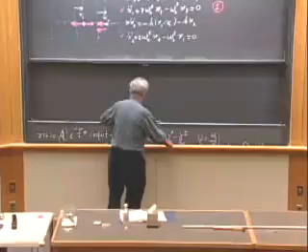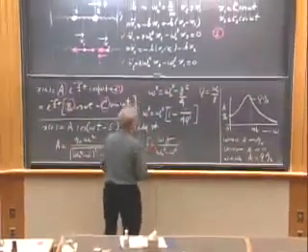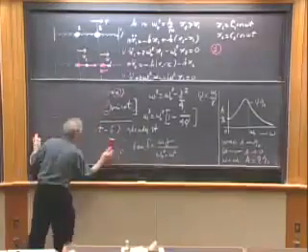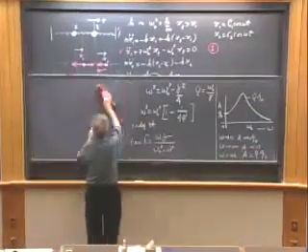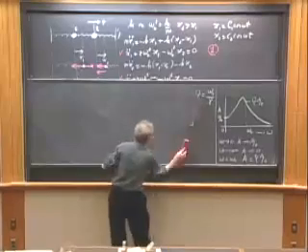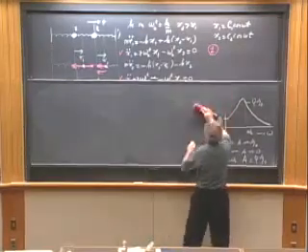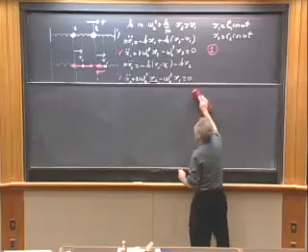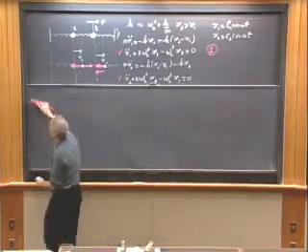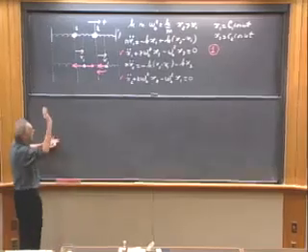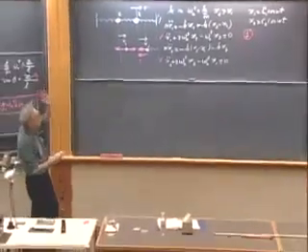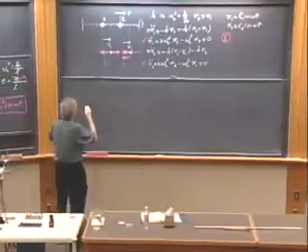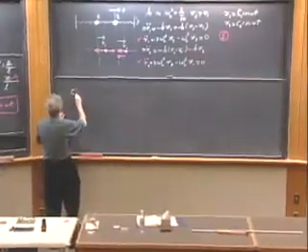And I may want to continue working on the center board, in which case I might as well erase this so that it stays a little compact. So I'm going to substitute this trial function into my differential equations. And every term will have a cosine omega t, so I dump all the cosine omega t's. So I go to the equation which has a big 1 there, and so that 1 becomes c1.